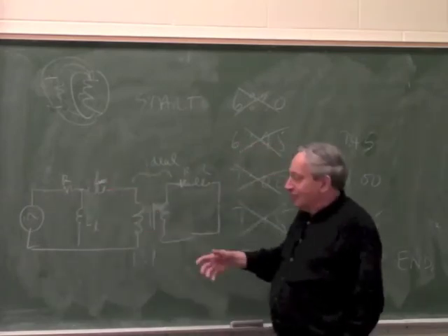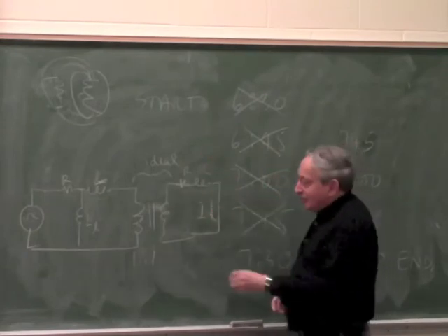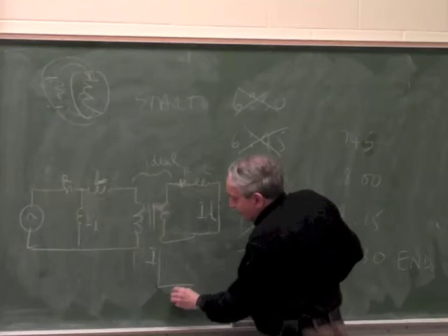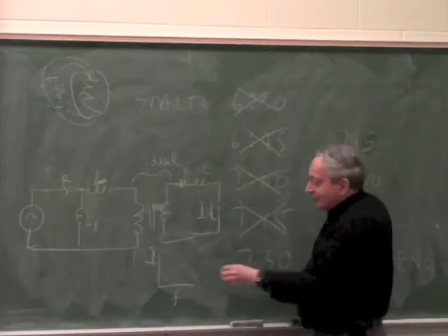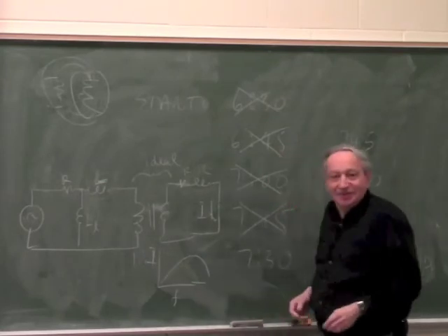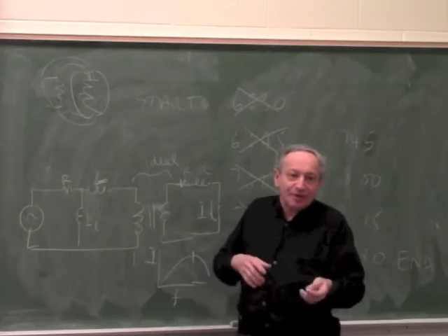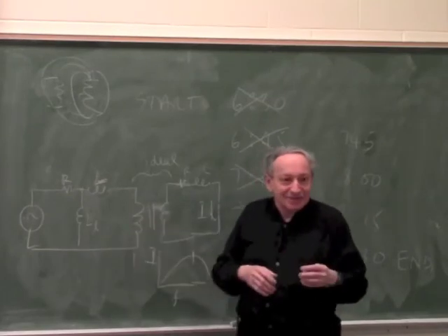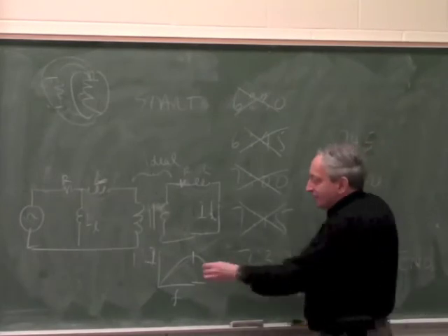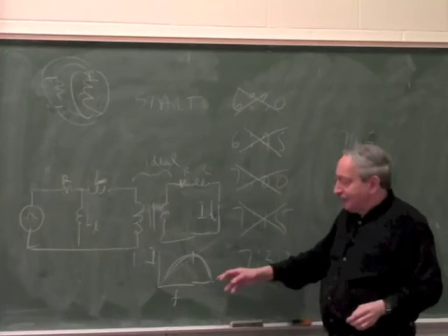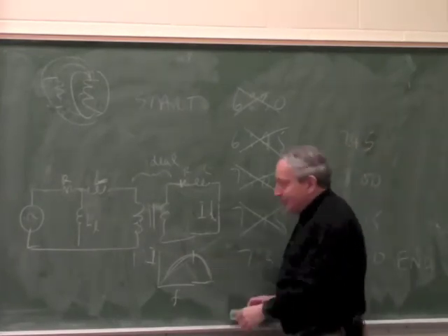So if you draw I, which is the same as torque in a motor, versus frequency, it doesn't look like it would in an ideal transformer. It actually looks like this or something. So you can optimize this point by playing around with how much copper, how much iron, how much resistance, and so on. Because every transformer, if you look at a wide enough frequency, looks like this, because at very high frequency the transformer doesn't work. So optimize is where to put the maximum point.